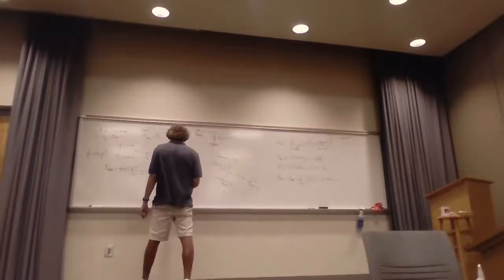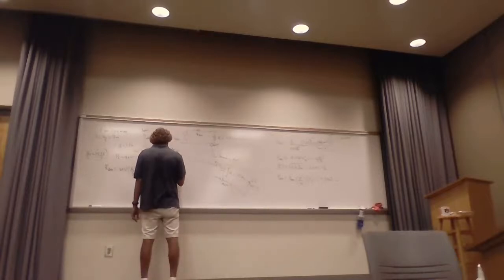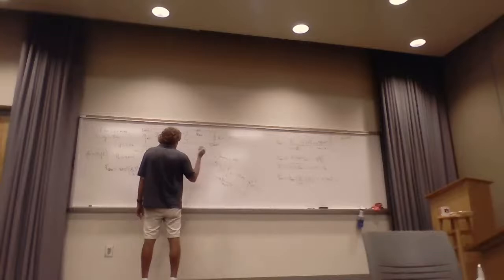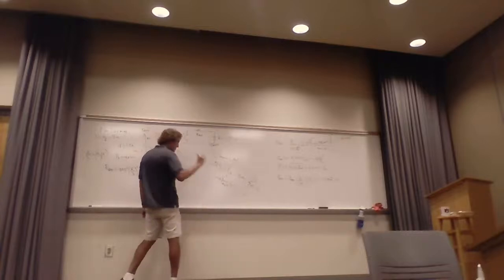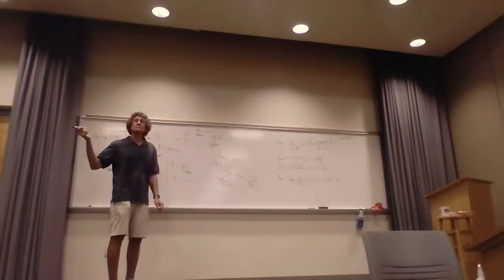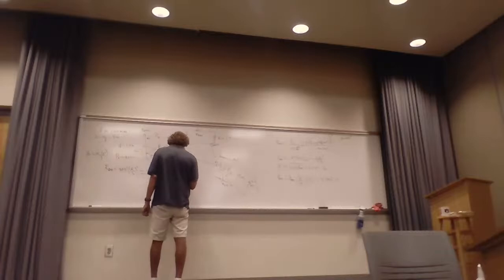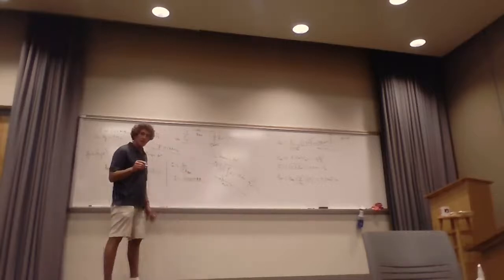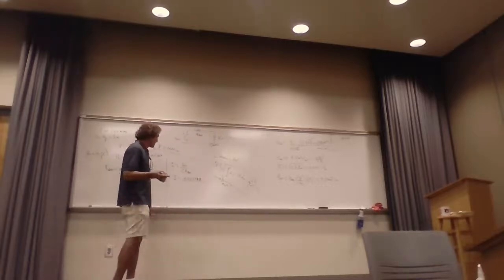But for this one, some of you calculate the current first, and that's fine. I itself would just be VOC over 2 R rad, because the actual load is R rad, and that would be the current. Can you tell me what the magnitude of that current is? Yeah, 0.0029 amps. Yes. Get that? Okay. Yeah, 2.2